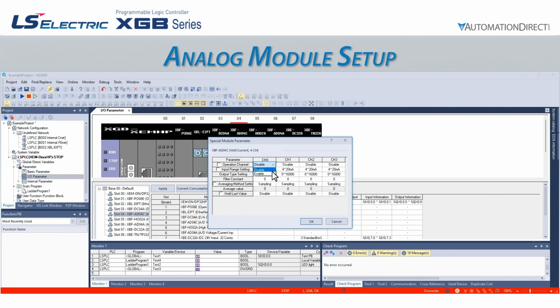The operation channel setting enables or disables each channel. Disabling channels will increase the module refresh rate slightly, so it is always recommended to disable channels that aren't in use. The input range setting deals with the analog signal coming in. If it is a current or voltage-only module, you can adjust the input range. If the module is a voltage or current combination module, like ours is, we can actually adjust both the range and the type of analog input. It is important the physical dip switches on the module match the type of input.